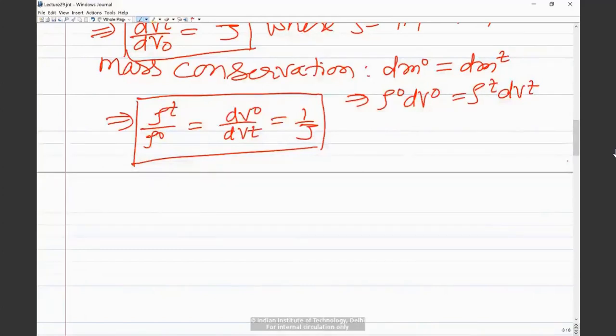So if we take a parallelepiped in the reference configuration itself, then you have to specify in which direction those edges are, and the expression for volume will also be complicated. So it is general enough that we take a cuboidal element in the reference configuration, and that translates to a parallelepiped, and we can easily relate these differential volume ratios. So we can always take any differential volume in that manner.